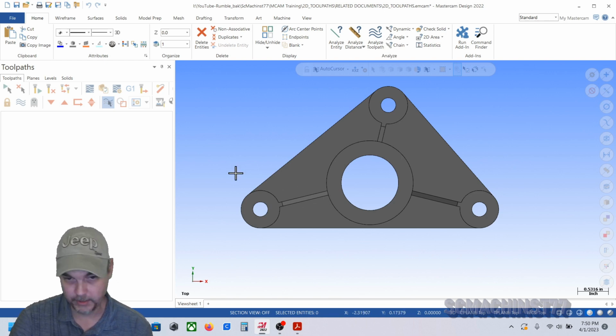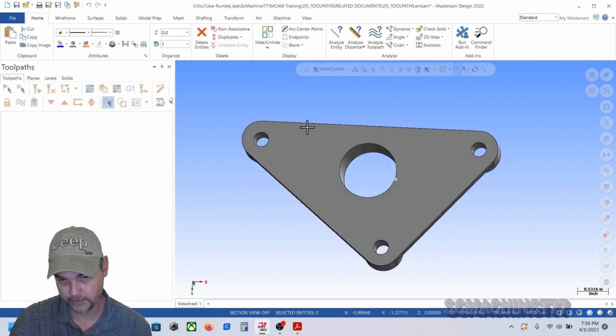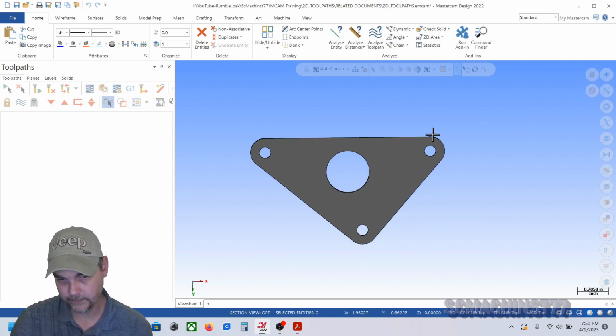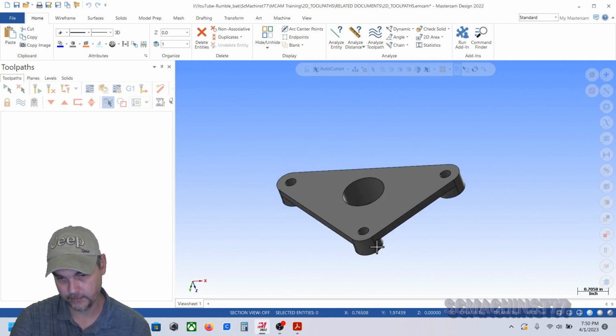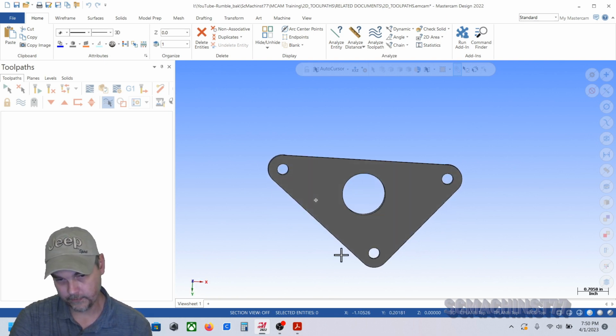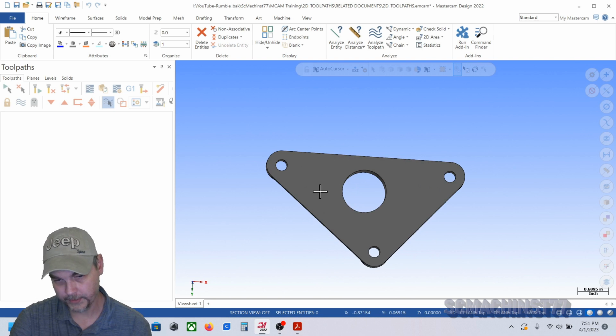then the next op will be, just like I said before, we'll probably hold it this way. It'll get straight, and then we'll come up with a set of vise jaws that we can just clamp it in. I think as long as we don't put too much force on it, we'll just have a step for it to sit on back here, and then create some kind of cavity for it to sit here, even if we've got to use these four points, or three points here, I'm sorry, for it to sit down on. And we'll get more into detail on that.